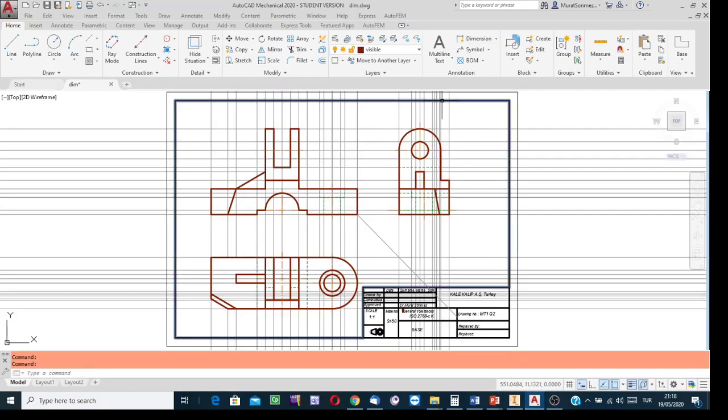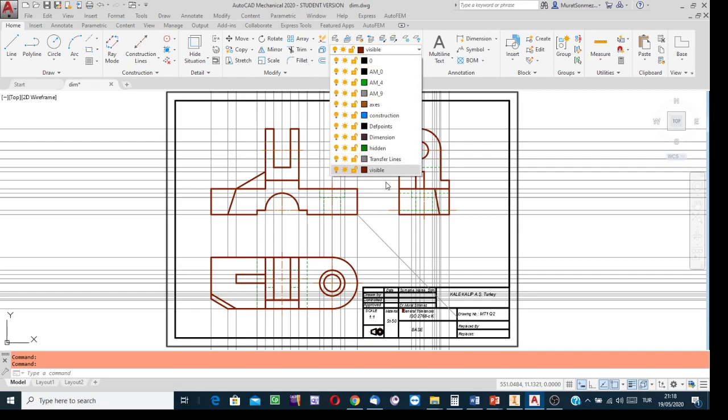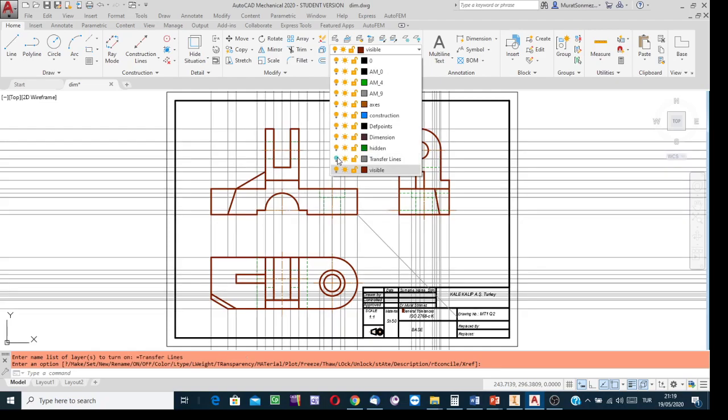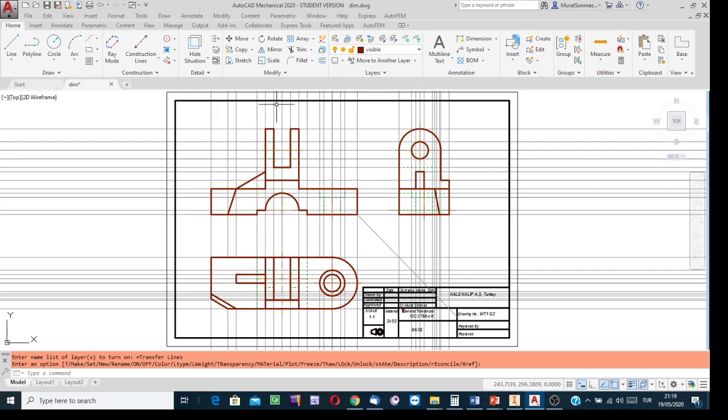In AutoCAD, yes, I said that the views are drafted. I drafted them, not created. Didn't use solid model for having this set. Well, obvious, because at the background you see, opening the, asking the visibility of transfer line layer, how, drop the list of the names of the layers, and then turning the length of transfer line layer on. And then, make the content of that layer visible. And, you know, in the content of transfer lines, I have the necessary transfer lines. These are,